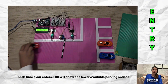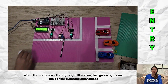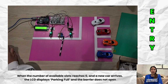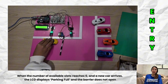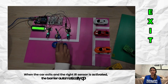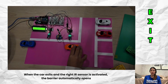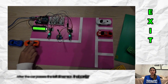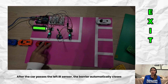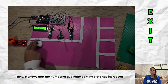When the car passes through the right IR sensor, 2 green lights turn on and the barrier automatically closes. When the number of available slots reaches 0 and a new car arrives, the LCD displays parking full and the barrier does not open. For the exit, when the car exits and the right IR sensor is activated, the barrier automatically opens. After the car passes the left IR sensor, it automatically closes. The LCD shows that the number of available parking slots has increased.